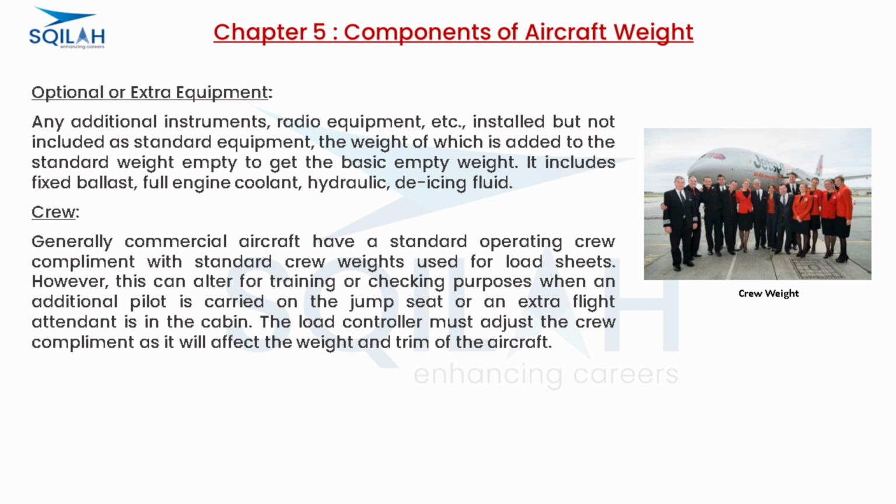Crew. Generally, commercial aircraft have a standard operating crew complement with standard crew weights used for load sheets. However, this can alter for training or checking purposes when an additional pilot is carried on the jump seat or an extra flight attendant is in the cabin. The load controller must adjust the crew complement as it will affect the weight and trim of the aircraft.